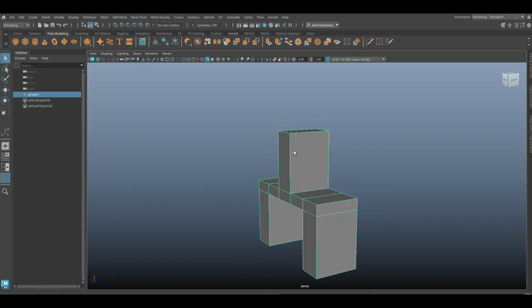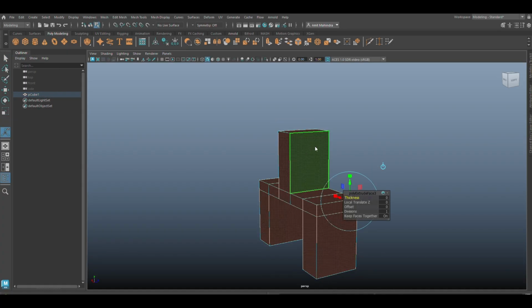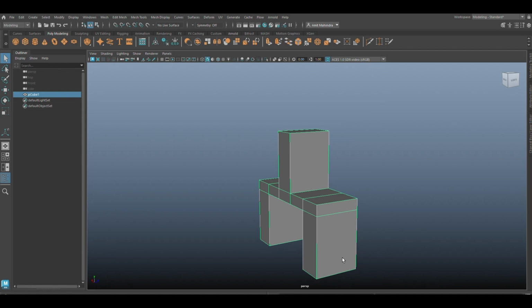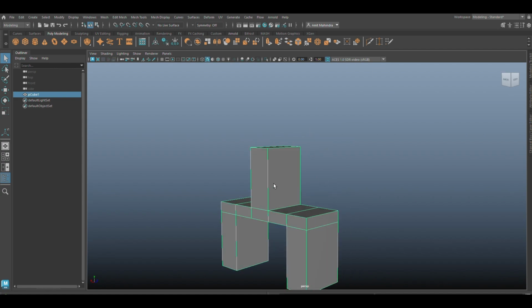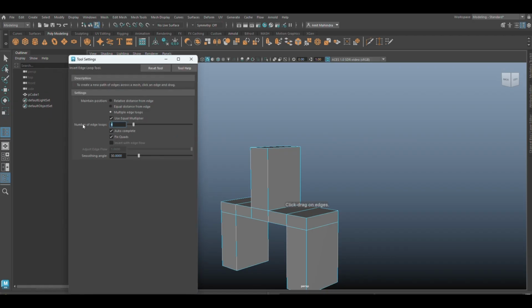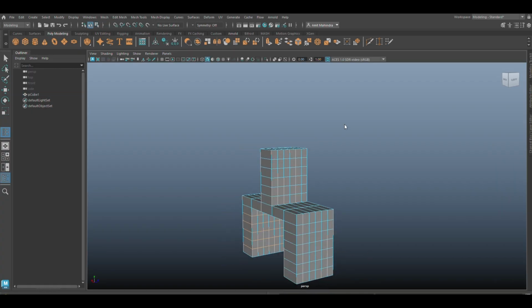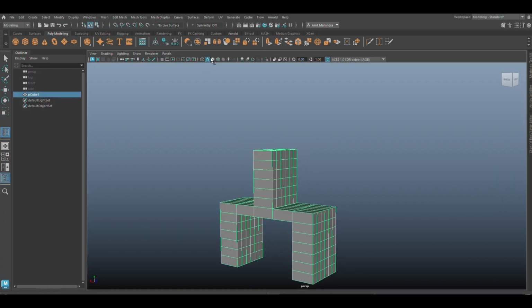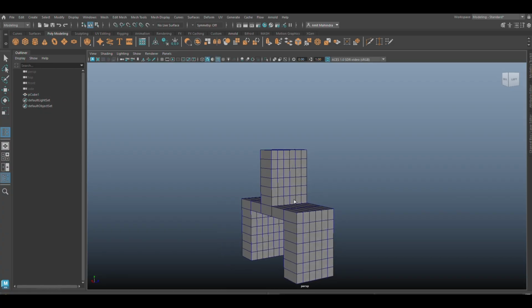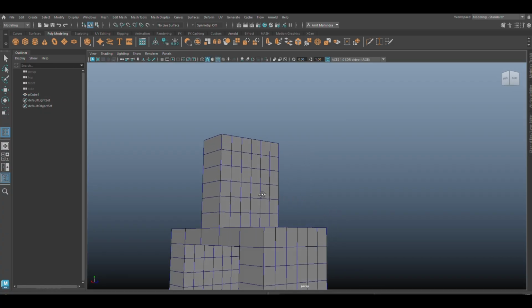So once we have that, we want to put in circularized components just right here, and here. To do that, all you need to do, apply edge loops here. So we go insert edge loop tool, select 5. I need number of edges 5. One here, one here, one here, and one here. Right? Once you have something of this, what do you want to do?